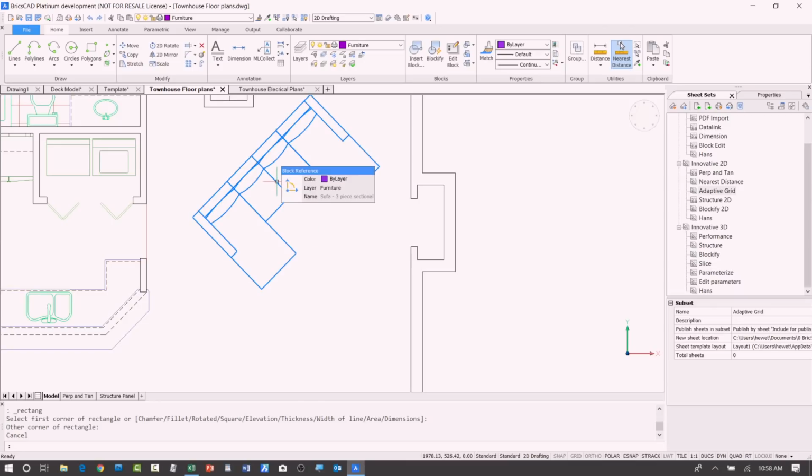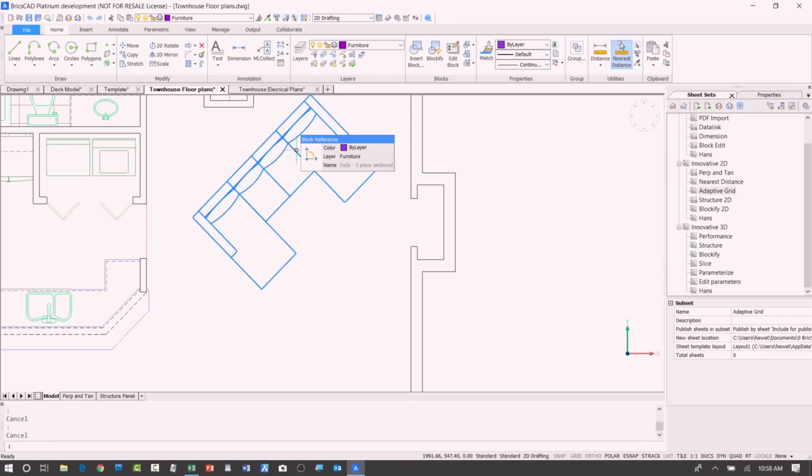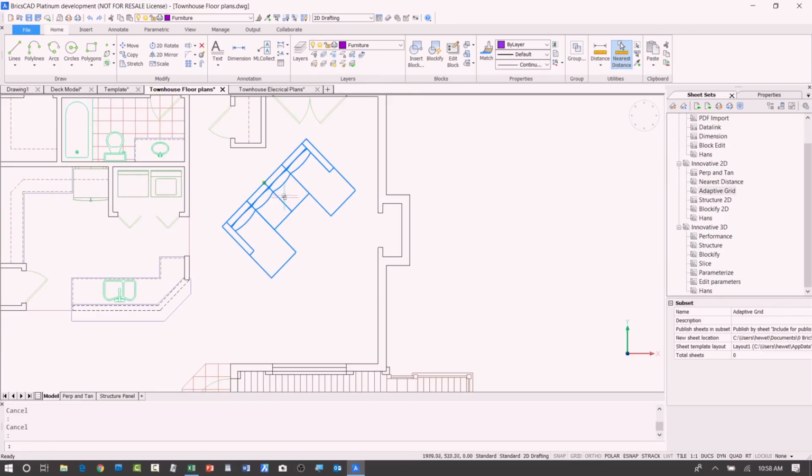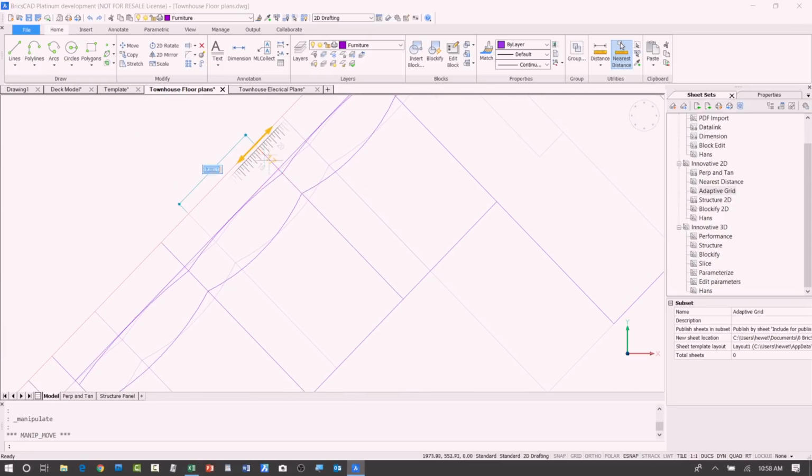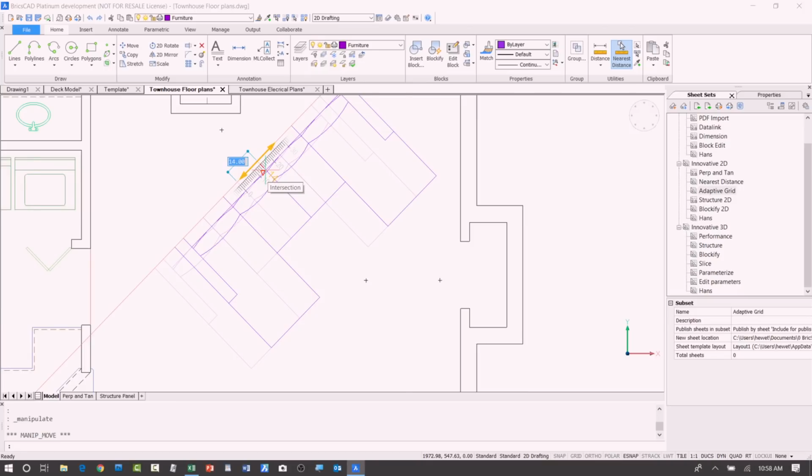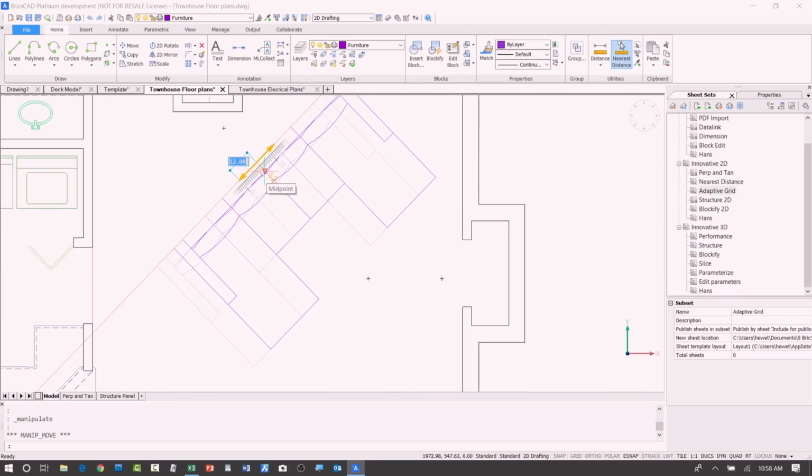For example, if I select this block here, this sofa, now if I use the manipulator, when I click on an axis, it actually displays this ruler telling me what the increment is. So just moving this, I'm not eyeballing it anymore if I want to move it a little. It's actually going to some grid value depending how far I zoom in or zoom out. And you'll see it in multiple places.